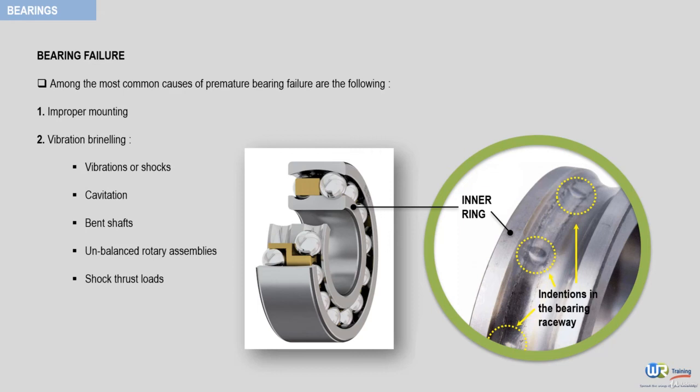It is like driving a car at high speed over a rough roadway. The surfaces of the balls and rollers begin breaking away, therefore destroying the bearing. All bearings coming out of service should be disassembled to examine the internal rotary and stationary surfaces.